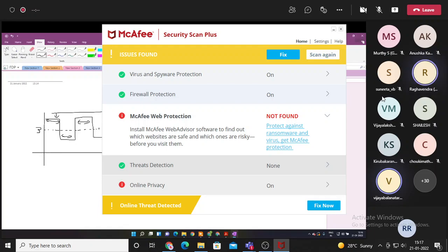Now that we are done with DC offset removal, we do thresholding. Anything greater than 0 is a 1. Anything less than 0 is a 0. And by 0, I mean the amplitude value over here. In this fashion, we convert whatever waveform we have received, because when you actually use light, this could be 0.2, this could be minus 0.2.